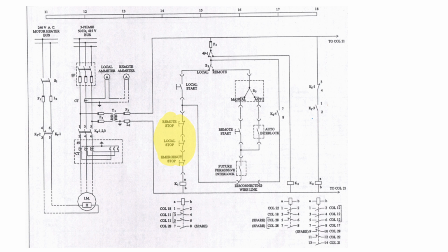Okay. Similarly, the motor can be started remotely by setting the local remote selector switch to the remote position and pressing the remote start push button. The motor can be controlled manually or automatically from the remote location using a remote auto manual selector switch. Okay, when the remote start button is pressed, the contactor K1 is energized, and the same process for starting the motor locally is repeated and turns on the motor. In most cases, the motors in power plants are operated sequentially.